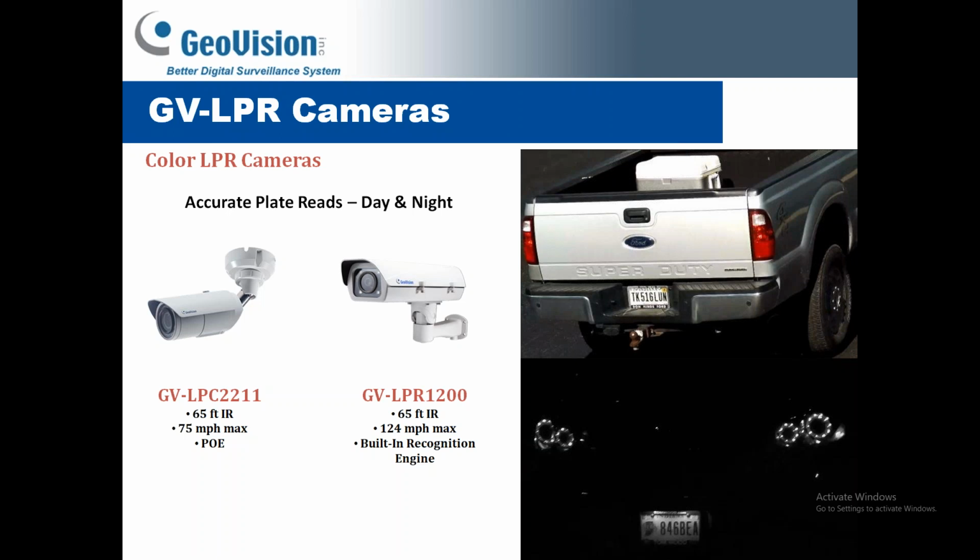And then lastly, license plate recognition. GeoVision is one of the fewer manufacturers in the industry that has true license plate recognition cameras. So these are cameras that are optimized for being able to see a plate both during the day and at night. One thing I will say is that license plate recognition is a trickier topic. These cameras really are meant to focus on like a 1 to 2 car width wide zone. You want to have them mounted and just looking and catching plates.